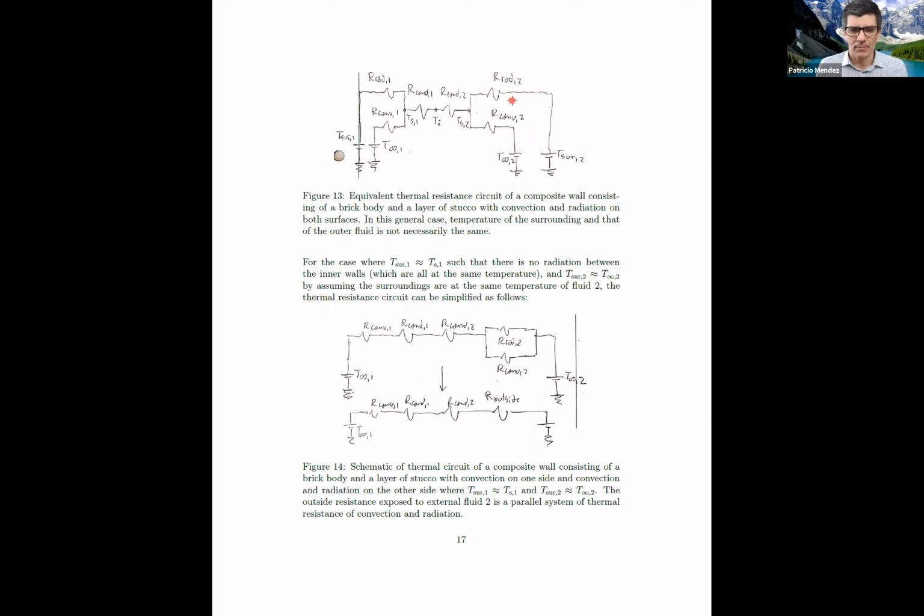I'll tell you why. This is the amount of resistance that was going out by convection. Resistance of radiation, whatever it is, can be small or can be big, it just opens a new path for heat to go. So in a parallel circuit, having more resistors in parallel, essentially all they do is take up more paths for losing heat.